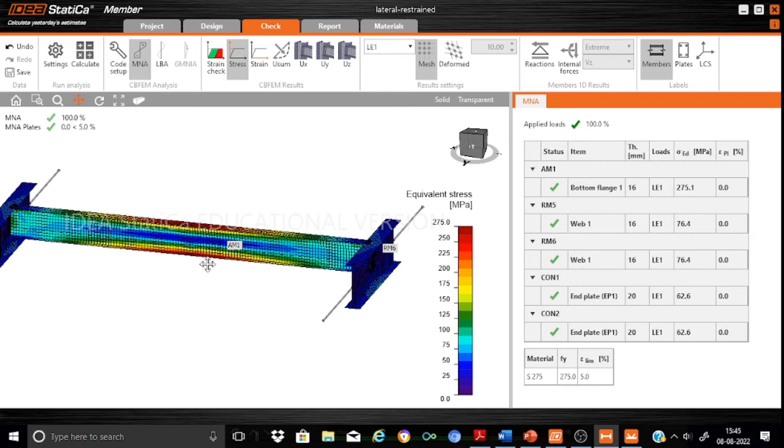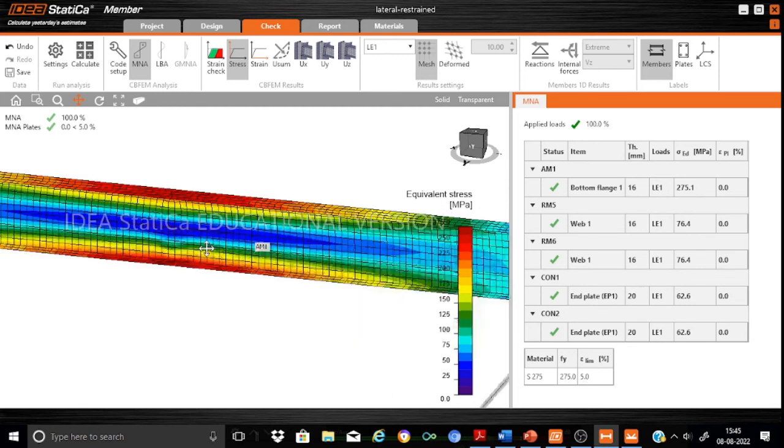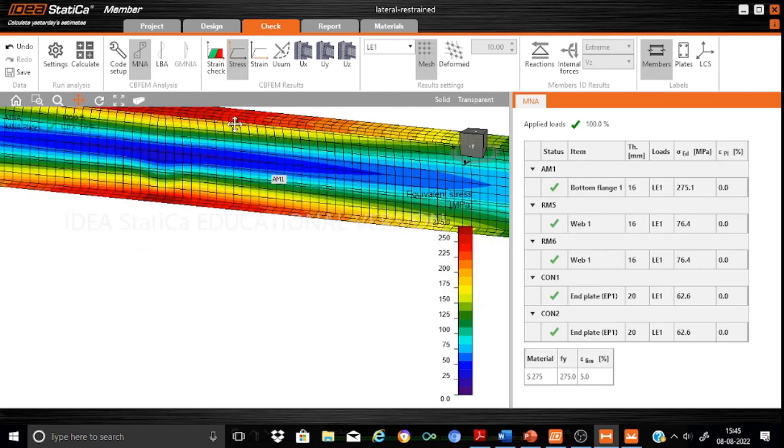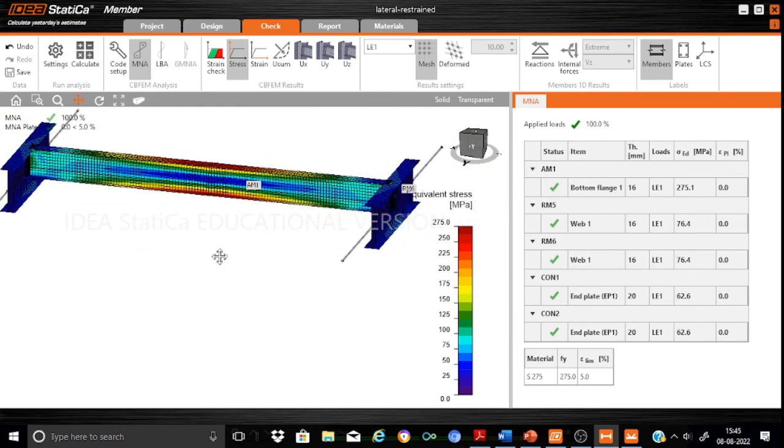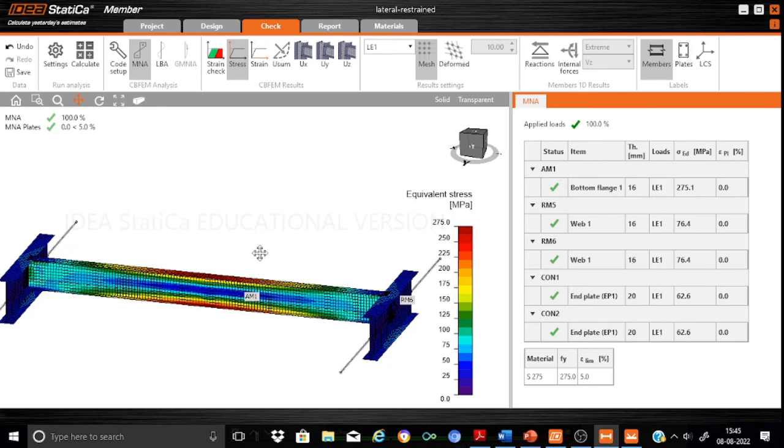Still, please remember that the Eurocode and the majority of international codes nowadays follow the so-called plastic limit method, wherein we calculate what we call the plastic moment of resistance on the assumption that all the fibers are fully yielded. Looking at this sketch, you will find that only some fibers are being yielded. That means the section does have some more capacity, or we can conclude from the strength analysis that the section is good enough. Now, this part is good enough. You can carry it out both for a restrained beam or an unrestrained beam.